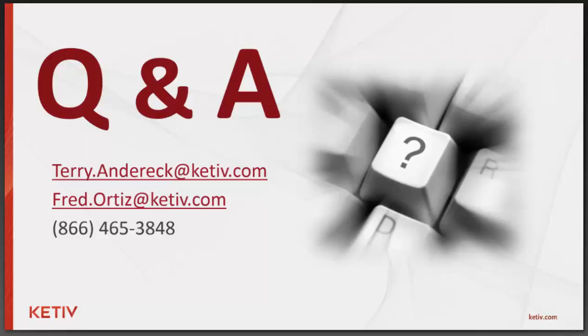That's a great question, and that's come across a few times with our customers. So if you do lose an internet connection, you are able to work offline, and there are a few steps to accomplishing this. One of the steps is downloading or saving as your model locally and working back in the traditional Revit project method on your network, and waiting for your internet connection to come back up, and then you can reinitiate your model back to the cloud when your internet's back up. So there are workarounds.